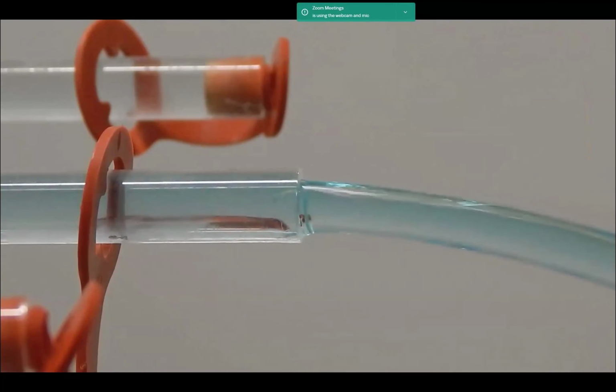He was saying, look at the white flash at the right there, at the top. And then you'll see when it's laminar, it'll be a straight line. So what they're doing is sending ink from the left-hand side and changing the flow. Now, rho V d by eta, if I increase the speed, what will happen to Reynolds number? It will increase. So if I increase the speed of the flow, Reynolds number will increase and the flow becomes turbulent. If I decrease the flow, V will decrease, R will decrease, and the flow becomes steady state.